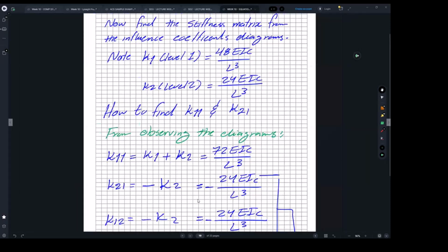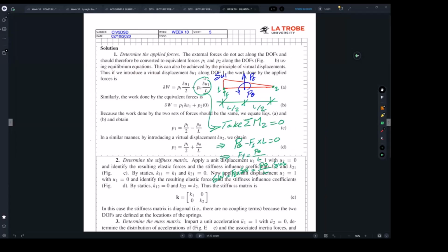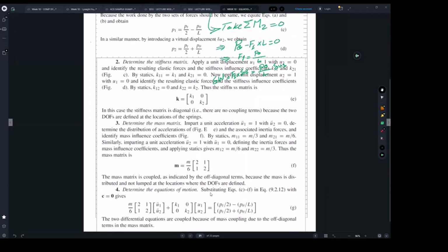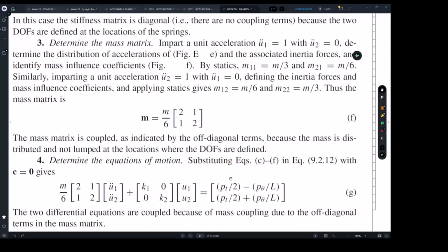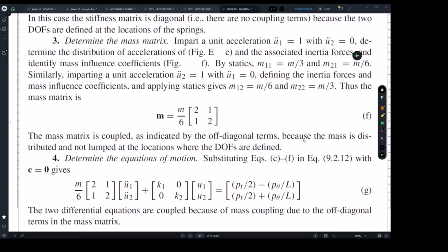So solve this without looking at the steps, then go through these concepts and these ideas, and eventually you will end up finding our equation of motion applicable for that roof beam system that would carry a unit like those chiller units and those dynamic units on top of floor. Same thing applies if you have a generator, for example, like a mechanical generator sitting on a suspended slab, and you need to check its dynamic properties. Remember, today we only developed manually, not by computer.